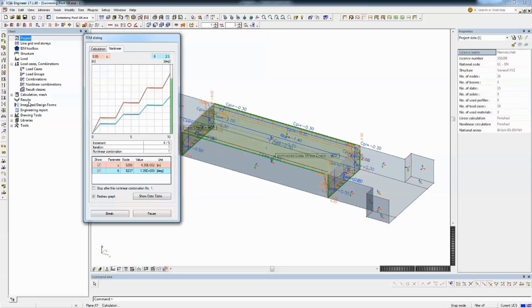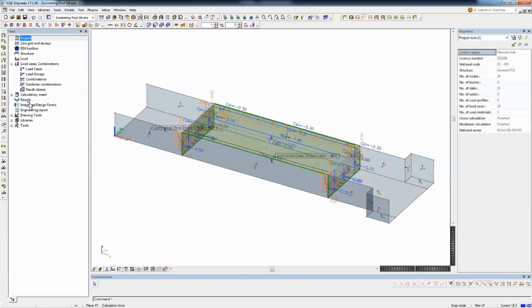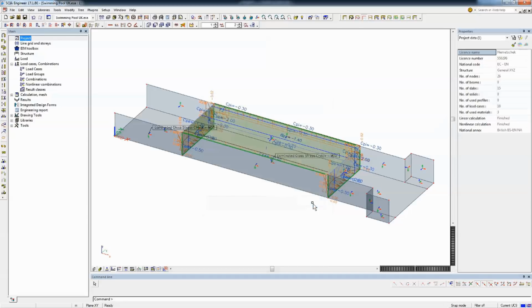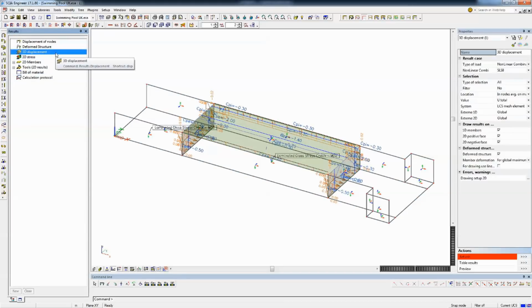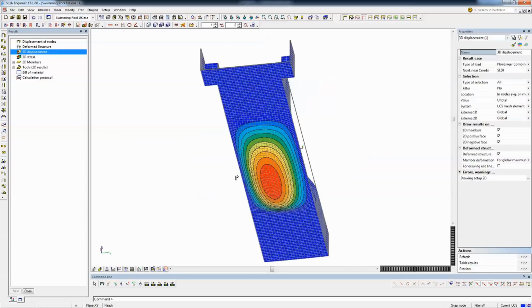SIA has a very fast FEM analysis engine. It's developed by FEM Consulting. I think it's shared with Drupal. They have the same solver. So it will bring a different solution from linear and non-linear analysis. Usually in non-linear geometric analysis, we have higher deflections but smaller stresses.